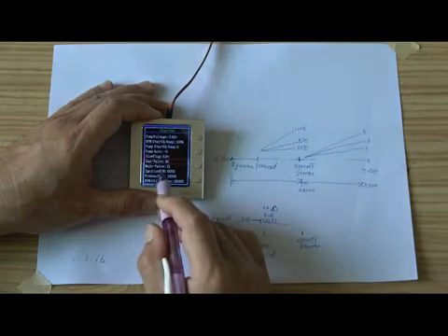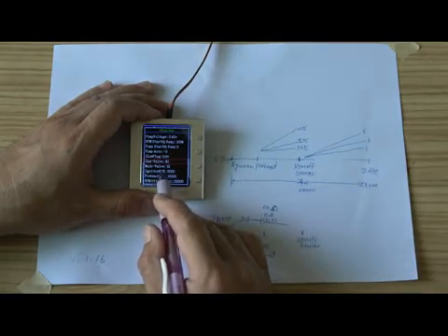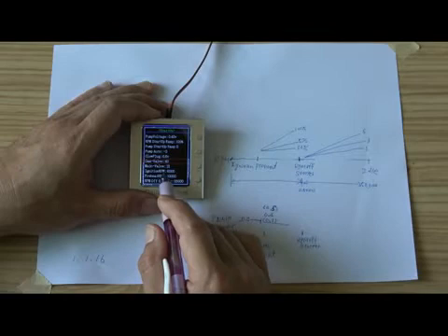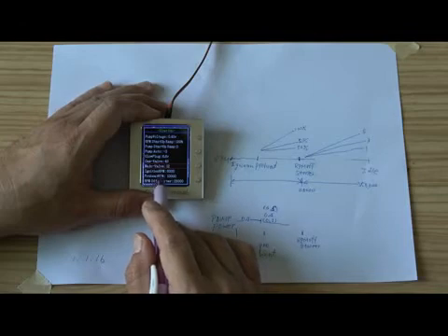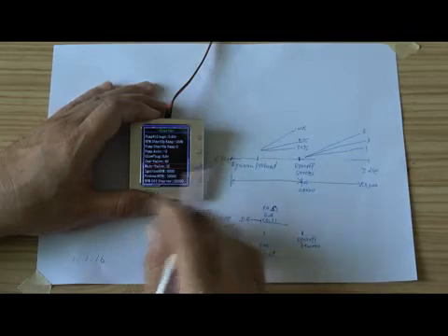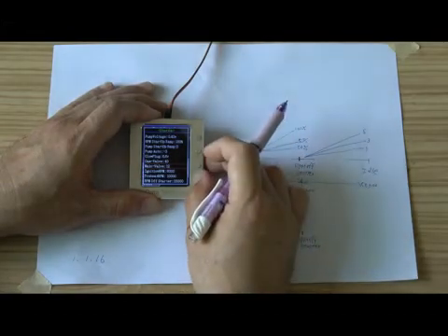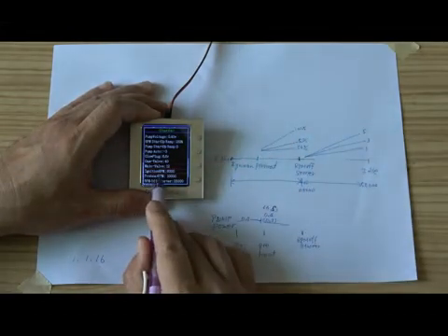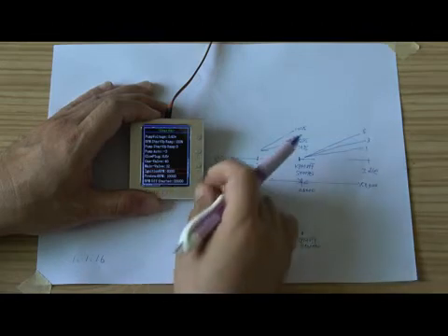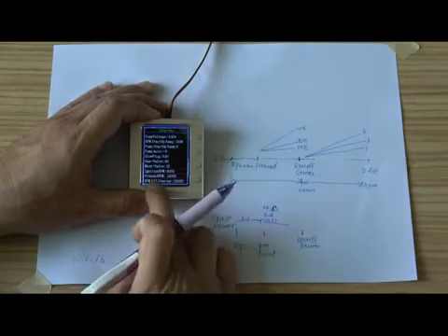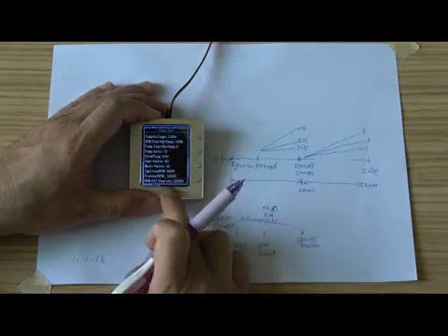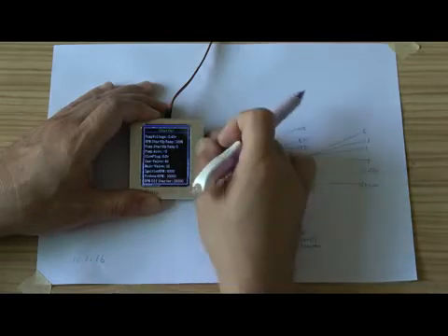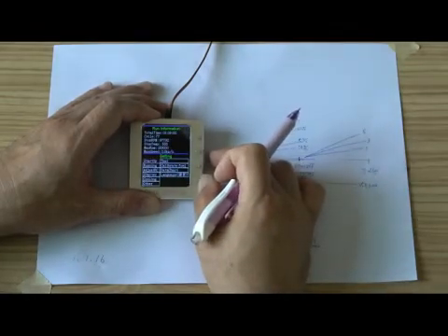Okay, the gas valve controls the ignition electric valve timing. The main valve controls the main ignitor open timing. Ignition RPM 6,000. Preheat RPM 10,000. RPM of starter 25,000. This is the startup manual.